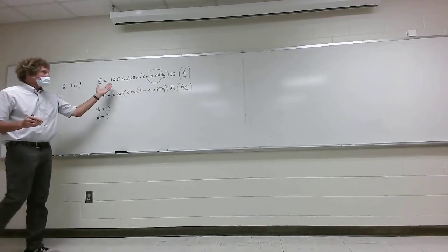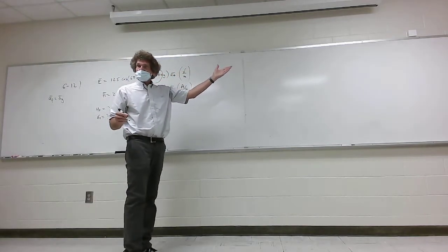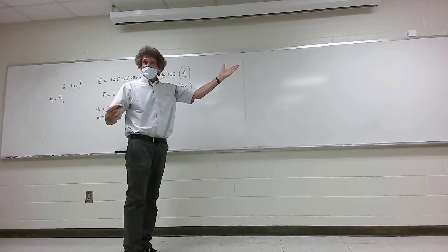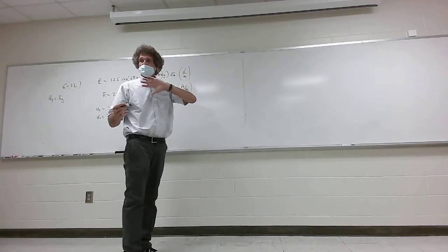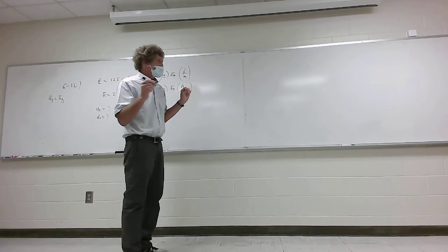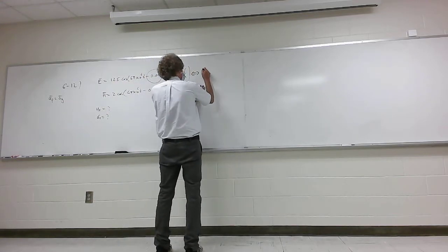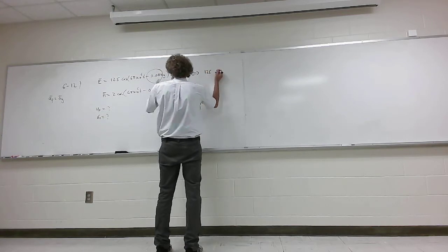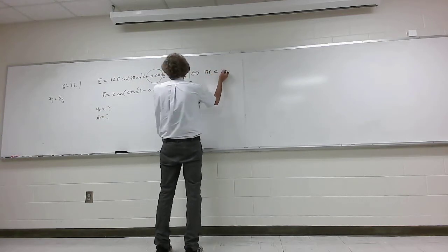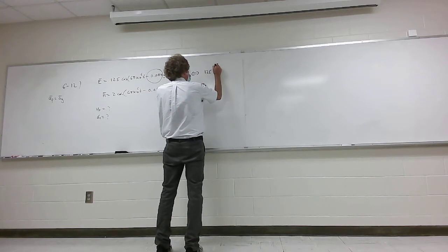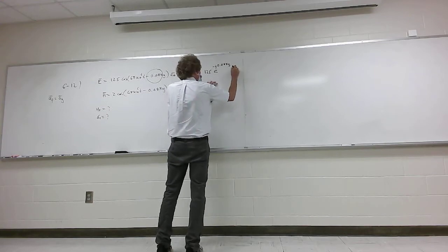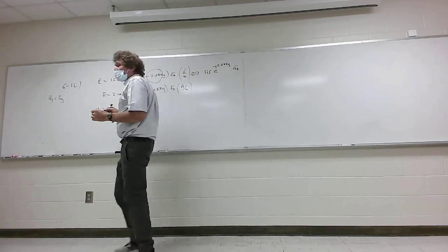Now, the phasor form of this waveform, I want to put down. And this you have to know like the back of your hand. There can be no uncertainty. The phasor form of this would be the same magnitude, then E, and you would just have this to the minus j 0.08 pi y, in the AZ direction. Y'all follow me? That would be the phasor form.